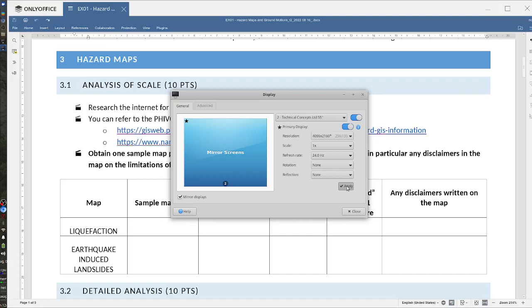Imagine you're here versus you're here. We call it the flagpole effect, or in technical terms, topographic amplification. They usually multiply the ground motion on level ground by a certain number to get the amplification that you will get if you're on a mountain or a building.